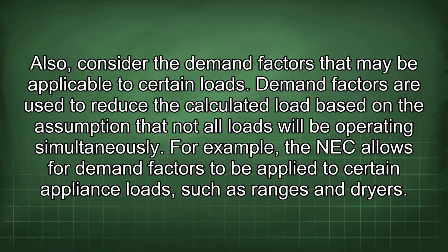Also, consider the demand factors that may be applicable to certain loads. Demand factors are used to reduce the calculated load based on the assumption that not all loads will be operating simultaneously. For example, the NEC allows for demand factors to be applied to certain appliance loads, such as ranges and dryers.